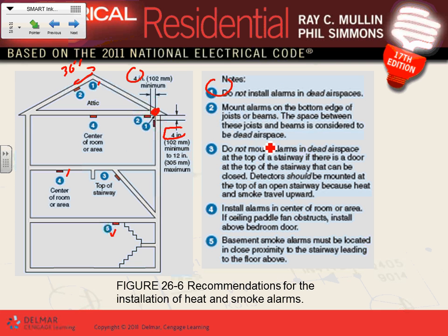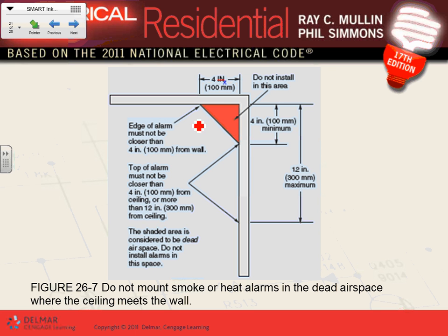Here's where the area is. Go back to here, where it shows the edge of the alarm, where you can't put it within 4 inches right here. Do not install in this area because the smoke is not going to roll over. It's not going to reach it.